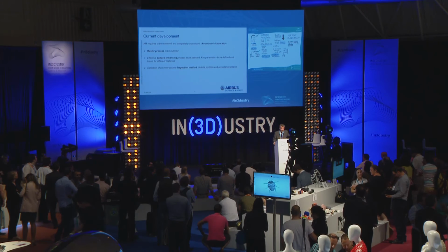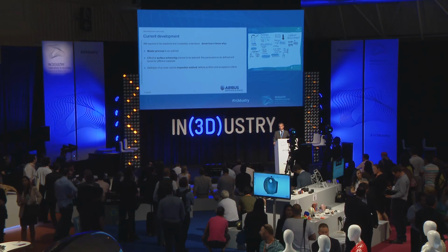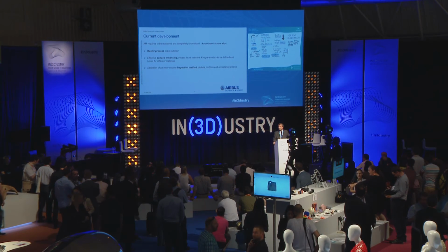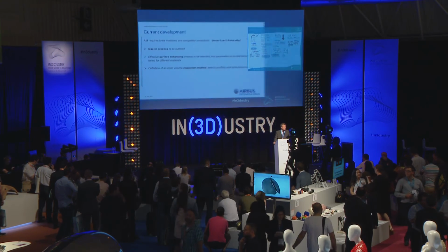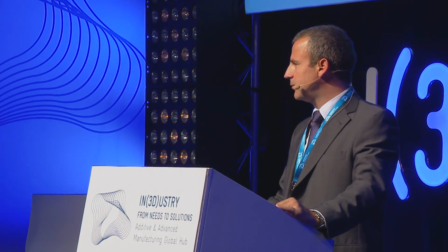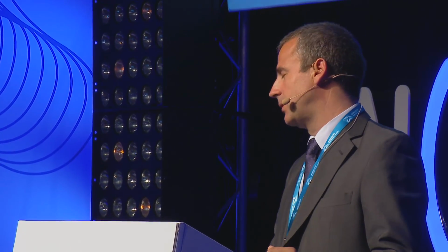I have talked about inner volume inspection. Microcomputer tomography seems to be the most promising technology, but perhaps for some cases it could also be possible to substitute it with a simple X-ray image that is post-processed. But the point is to define in which cases it's just possible to make an X-ray, because microcomputer tomography costs a lot of money for every single part fabricated.